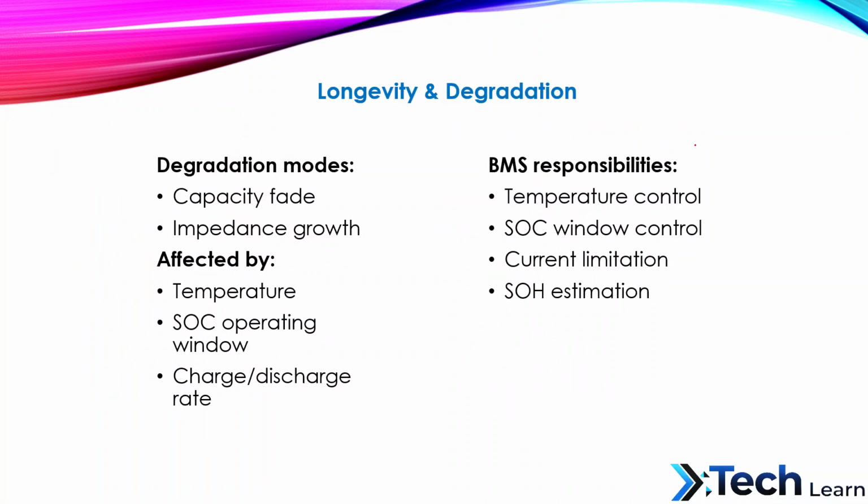Then coming to longevity and degradation, battery aging results in capacity loss and increased internal resistance. High temperature and extreme SOC accelerate the degradation. The BMS must manage the operating conditions to maximize its life. State of health estimation becomes critical in long-life systems.